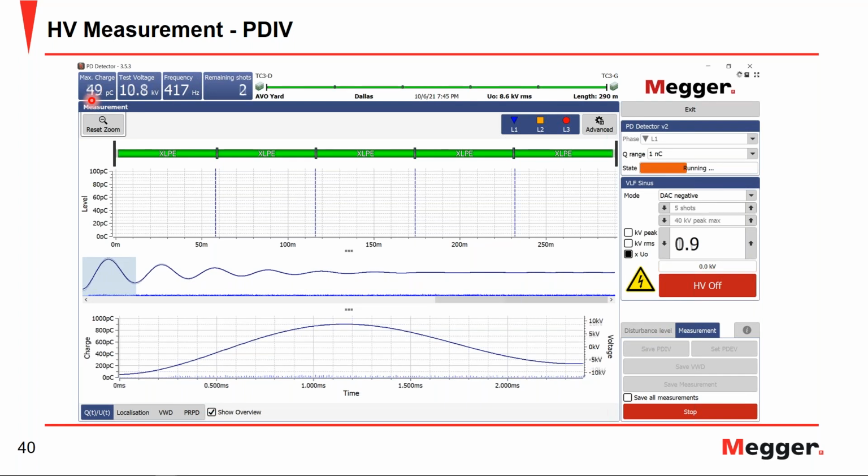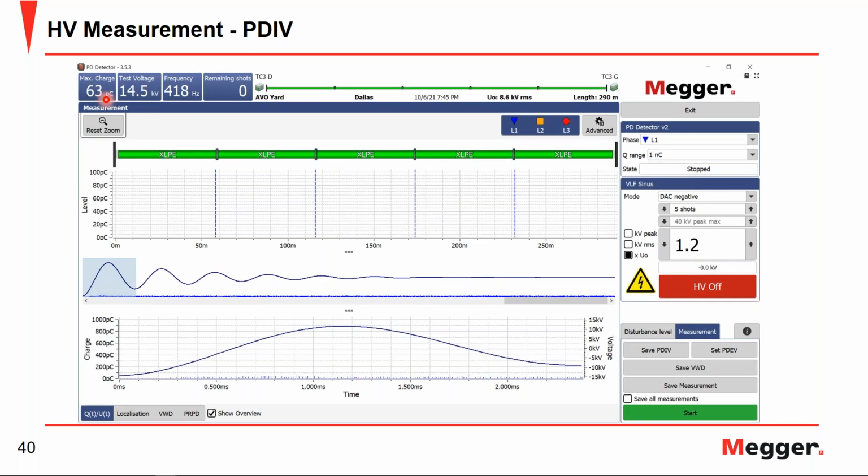So we want to go ahead. One measurement you always want to get is 1 times your RMS, just because it's a nice clean measurement to have. You saw I was stepping up by 0.2, but I always like to get that 1 for your reporting purposes, but still just background noise. Finally, we went up to 1.2. I'm still doing our 5 excitations per voltage step, but now we can see our charge went up just slightly, to 63.